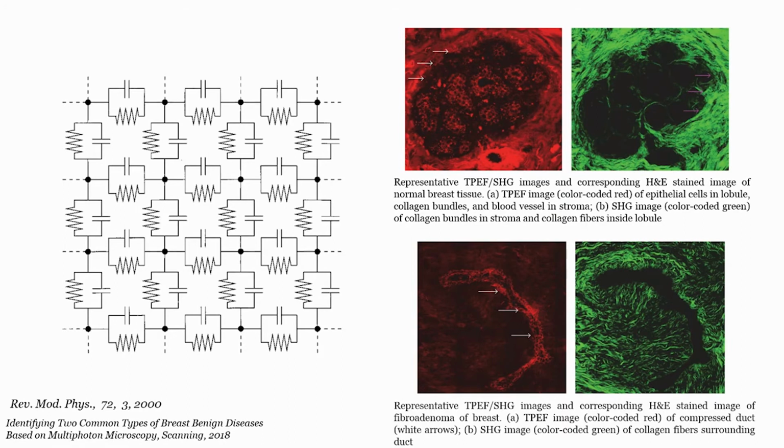This brings me to the frequency dependent conduction in disordered systems. This particular aspect will be clear from this particular slide. So let us have a look at it. Here what we have done is the entire composite network of conducting islands and non-conducting regions in between them is converted into a unit resistor connected in parallel with a capacitor. How do we arrive at that?